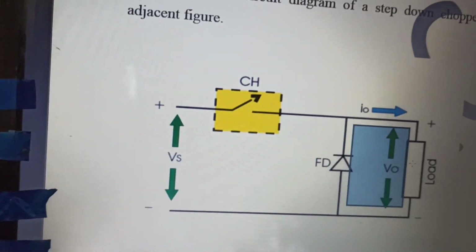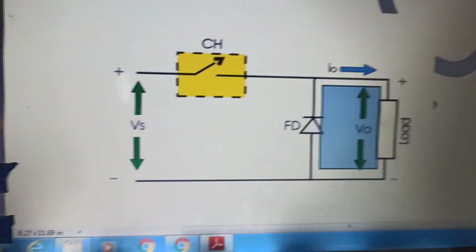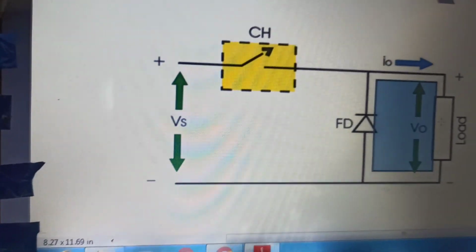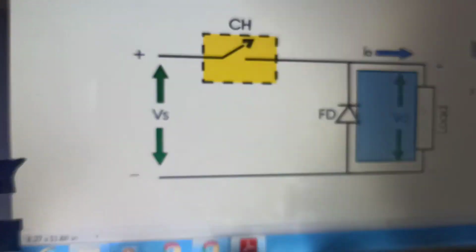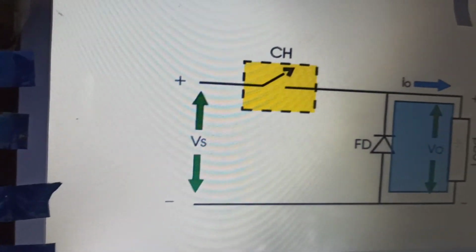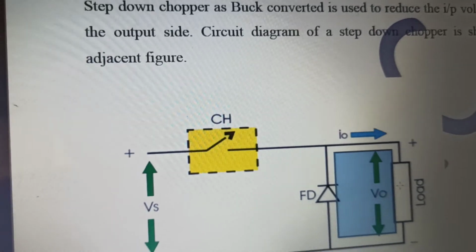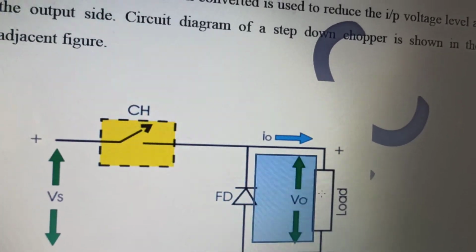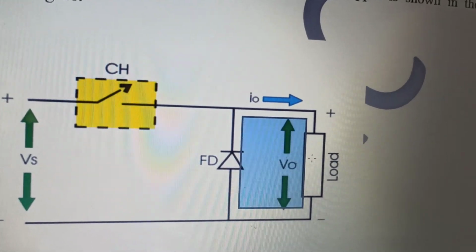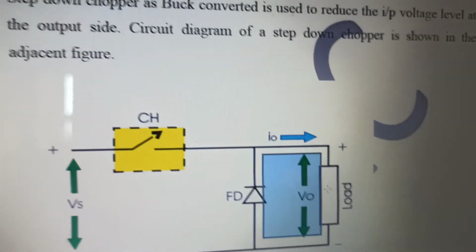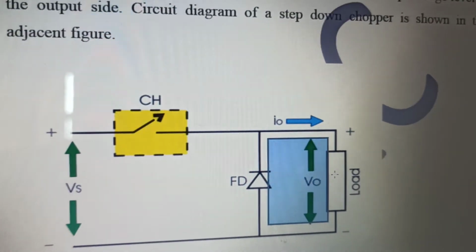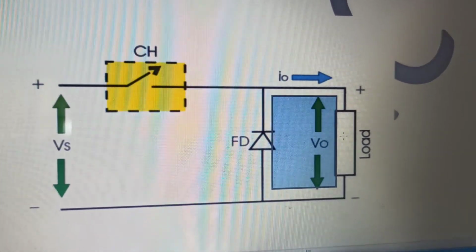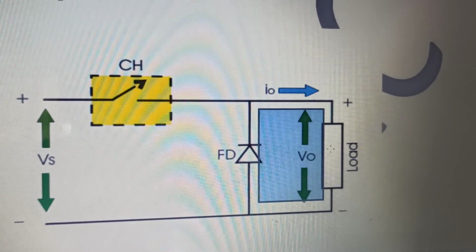So I hope the basic chopper circuit is clear from this diagram. How the chopper will operate. It will simply comprise a simple RC circuit, and through the RC circuit we can get the values of voltage at the end of each cycle. It's very easy. You have to simply take that value at t, by putting the value of time equal to T by 2, and we know that the voltage at infinity and voltage at 0 can be calculated, and we can complete the analysis.